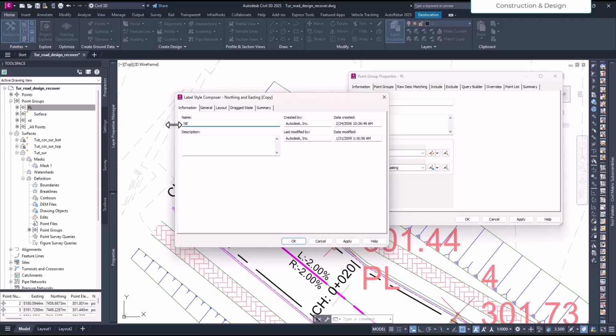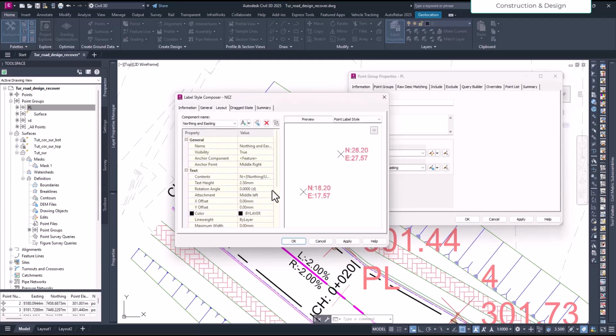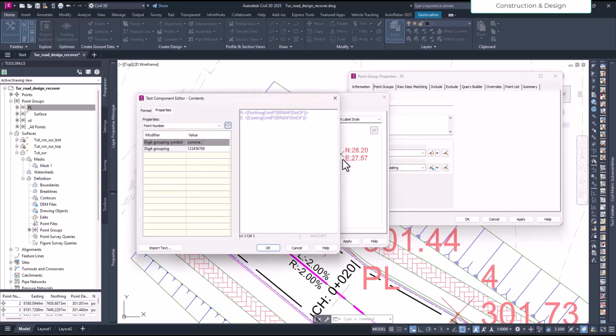Okay, and in the layout, northing, easting is already there. So I will just put the elevation parameter there. So we'll add point elevation, with the same accuracy and everything, whatever it is, and I will say Z. Okay, northing, easting, and Z in the same style. Okay, and say okay, and it will be like this.